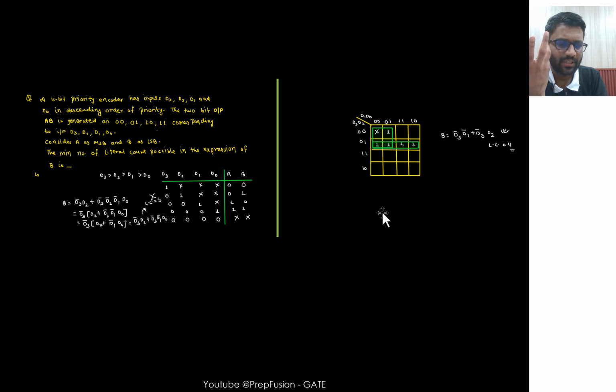Generally in priority encoder, I have seen n number of resources where this thing is taught absolutely wrong. They will tell you just a standard circuit, and with respect to the output given, you directly write down the expression in terms of D0, D1, D2, D3. But that is not correct. You always need to make a K-map. I have taken a question where, if you directly write down the expression, your answer will be wrong. So you have to make the K-map there.